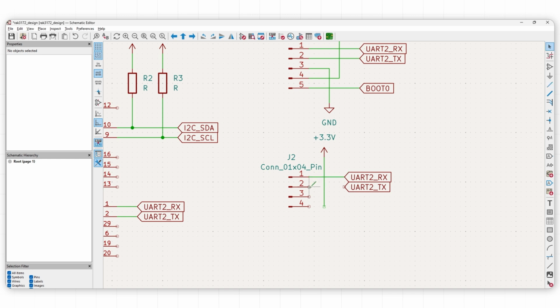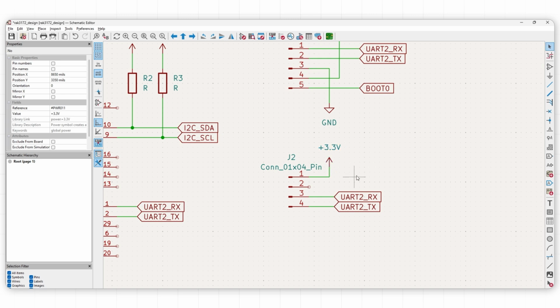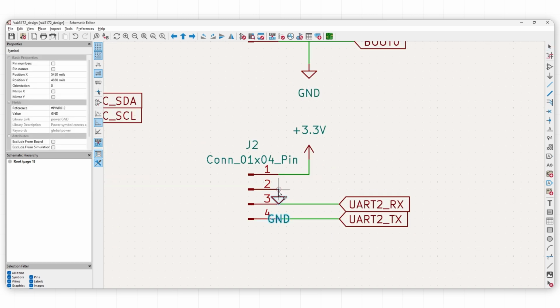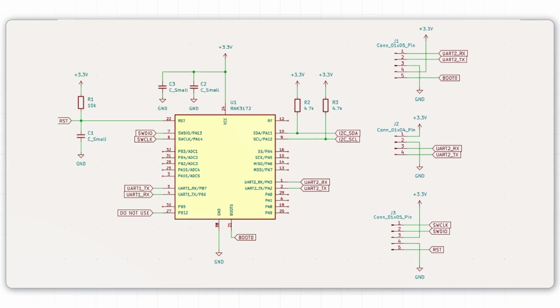6. It is recommended to make UART1 accessible. One approach that you can do if you use the RAK3172 as an external LoRa or LoRaWAN modem with external MCU is to reserve UART2 for FW update and UART1 solely for AT commands. UART1 by default does not accept AT commands, but it can be enabled via custom firmware using Serial API. After all these considerations, your schematic diagram for the RAK3172 LoRaWAN module is now ready. Here's the complete schematic for your reference.